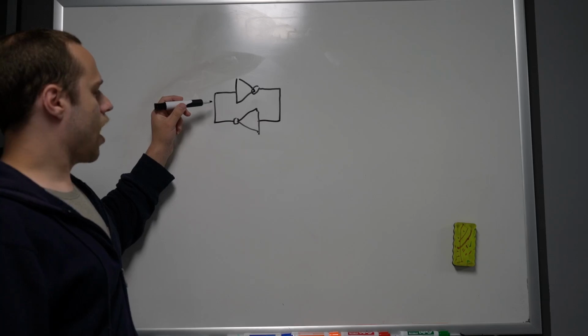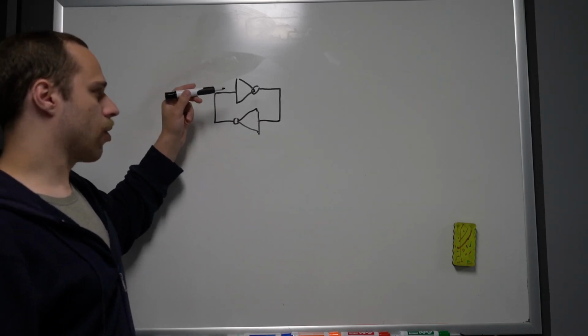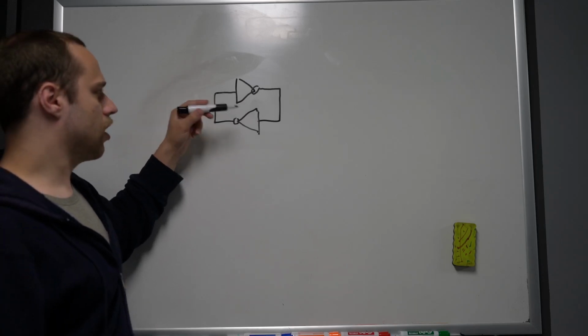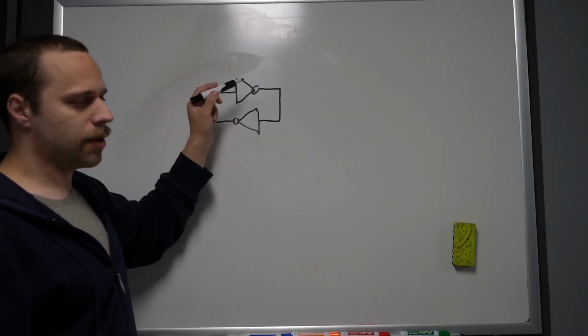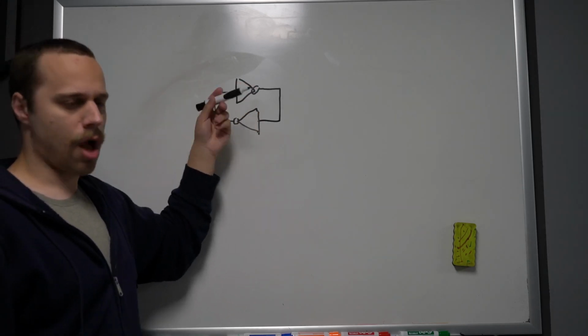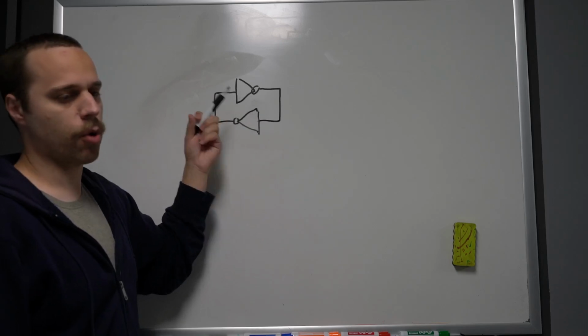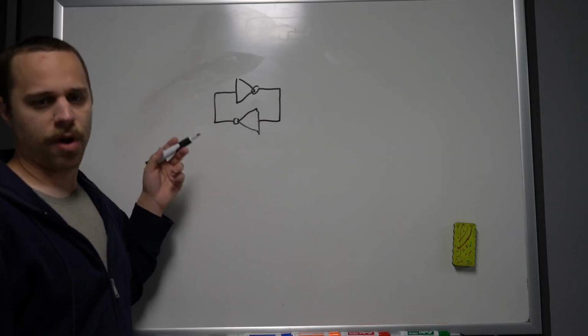So this forms a stable circuit. It will power up in an unknown state. One of the inverters will have a slightly lower VT than the other, or slightly higher drive strength, and it will end up creating a positive feedback loop. So which half ends up being high and which half is low is not deterministic, but it will stabilize very quickly after power up.